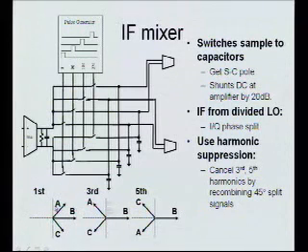So here's the fundamental. If I add up those 3 signals, they pretty much add in phase. They lose a little bit because they're not quite lined up, but it's pretty good. But the third harmonic, this 45-degree split becomes 135, and this negative 45 becomes negative 135. And if I just weight it right and sum them up, they cancel, and I get nothing. The same is true for the fifth. Basically, you can just see A and C is swapped here. And I get to the seventh, and I'm back to this situation.